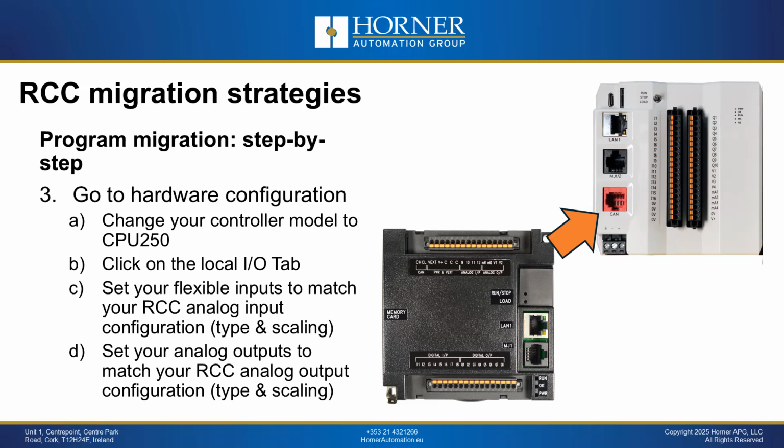The RCCs did not have any options for the most part with their digital inputs. For the most part, they did not support high-speed counting except for RCC 6512, which is a high-speed counter coprocessor. All the rest of the models did not do any high-speed counting at all, so there is not much configuration that will be required there.